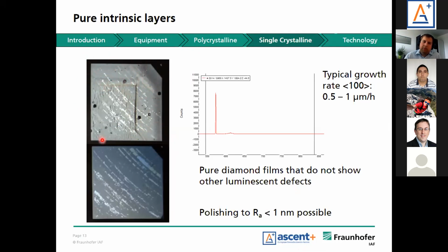With CVD diamond, I used this image to show you a few features that sometimes occur. Even the HPHT grown diamonds have some dislocations. This sometimes results after overgrowth in forming these kinds of structures that are called hillocks. Apart from that, you have the growth sectors.